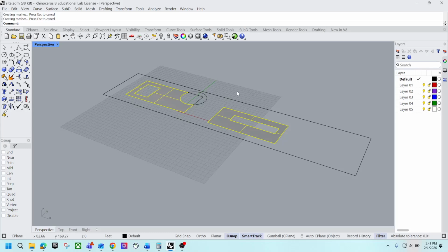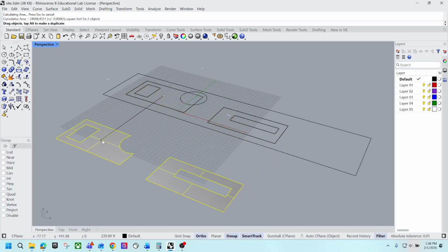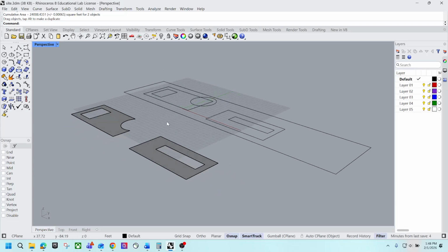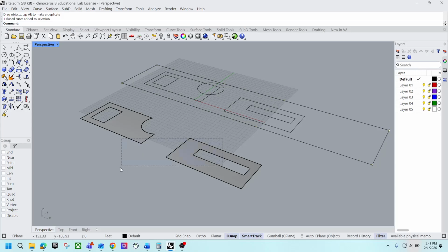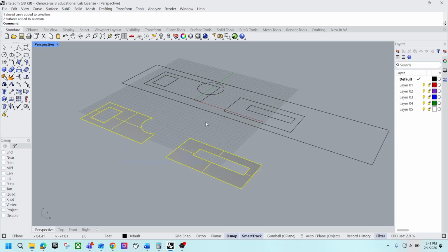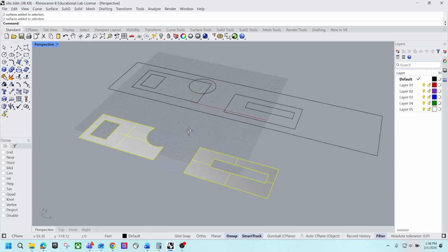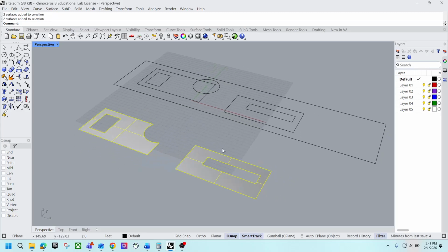So the way you can measure the area of these two is very simple. If you just type area, enter, this will be the total square foot based on this footprint. So that would be my way to generate the building footprint and calculate BCR, right? So if you figure out the total site area and then you have the building footprint, you can get a BCR very easily. You can also do this with Grasshopper. Maybe I will do that later after I talk more about FAR.